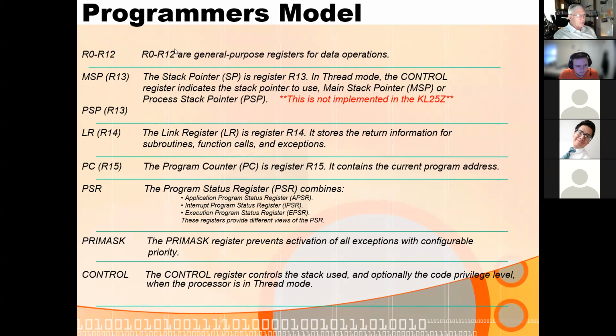Not all instructions can get to R8, 9, 10, 11, and 12, the 5 high registers. They are somewhat limited. But again, when we're writing in C, all this stuff is hidden away at a lower level of abstraction, at the assembly language level, which we don't really get to play in. But that's what's going on. And the 5 high registers are used for some of these advanced instructions.